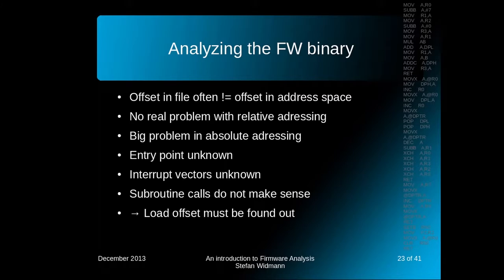We would not know where the entry point is, where we should start. Interrupt vectors might be decoded completely wrong. Subroutine calls do not make any sense. They go outside of our firmware, for example, or into the middle of instructions. So the load offset has to be found out.